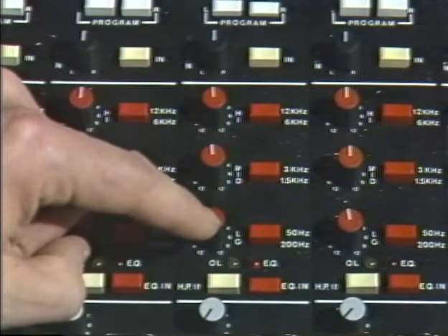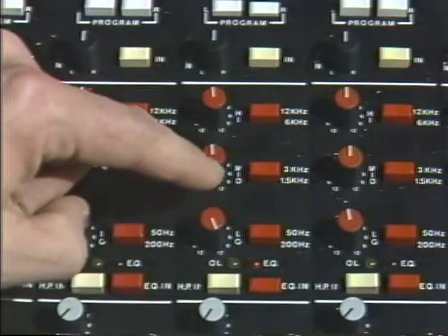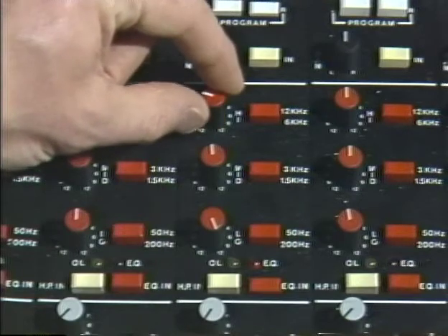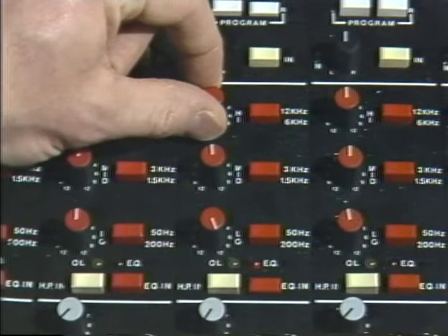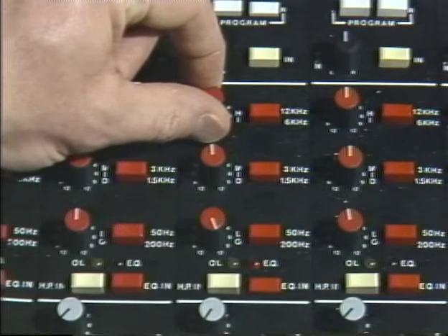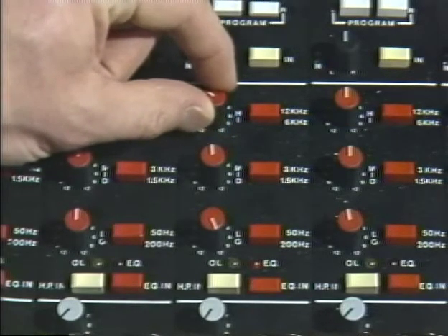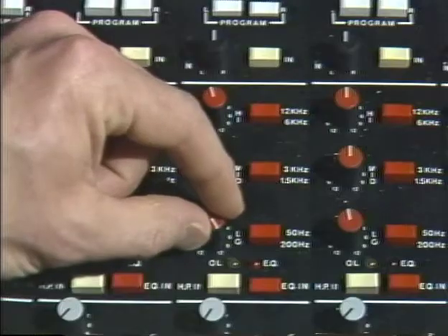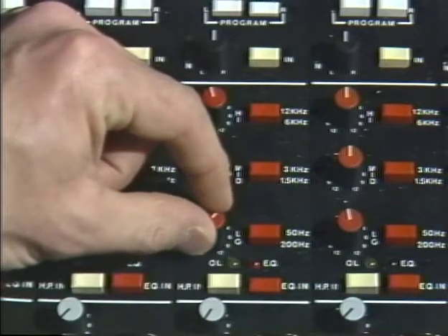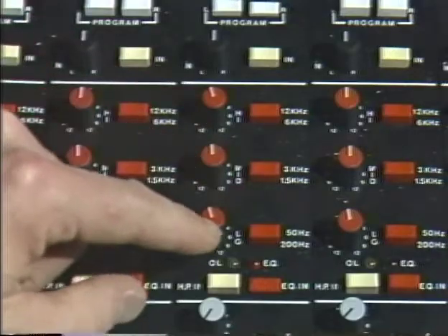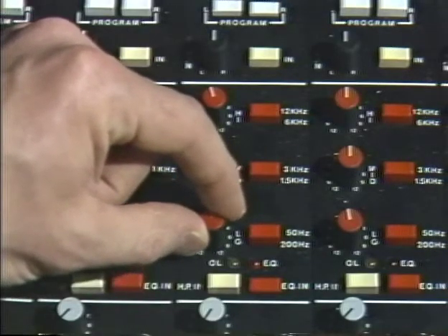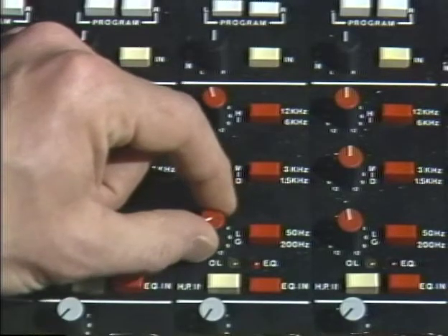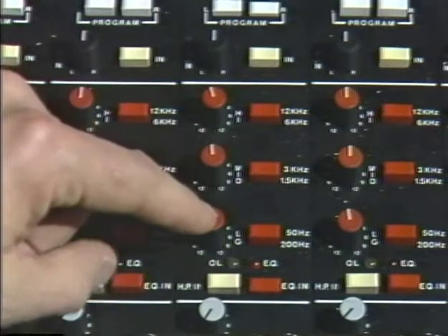And so that has a very bassy sound, and in fact we can make it even bassier by taking the high frequencies and attenuating those by 12 dB. Okay, well, let's put some of the high frequencies back in, and now let's turn the low frequency gain first back down to 0, and now we're back to flat equalization, and now I can turn the low frequency gain down so that I attenuate the low frequencies by as much as 12 dB, and that's where we are now. And so this has, of course, a much crisper sound.